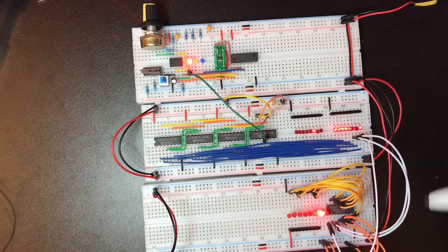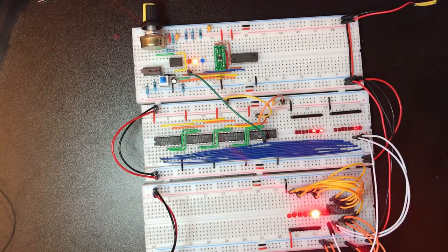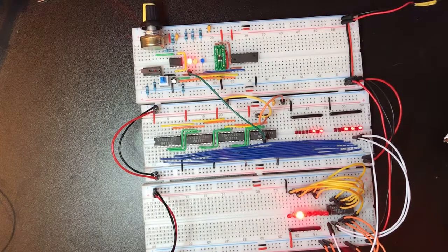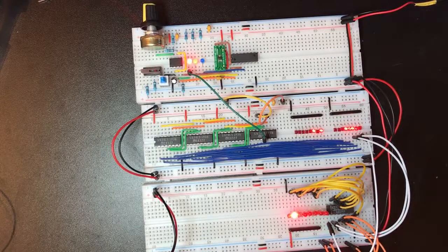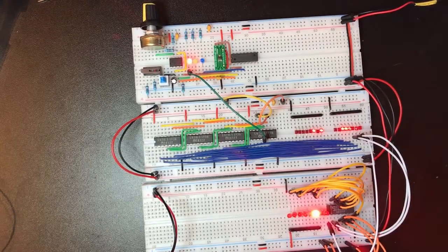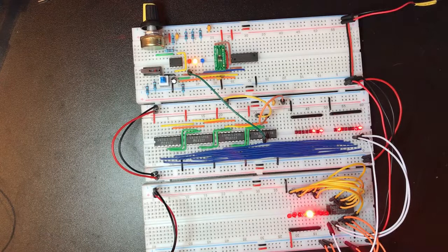So obviously, on those registers we're also going to have a load line. Now this is interesting because whilst we can only tell one register to output to the bus, we could theoretically tell multiple registers to read from the bus. Now this could be pretty handy if, let's say we wanted to reset lots of registers to 0. We could load a 0 into one register, push that onto the bus and tell all the others to load it.